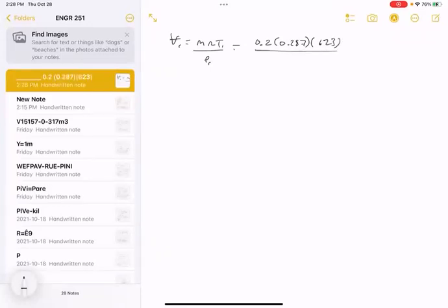The pressure in the initial state, so nothing's happened yet, is 2.5 megapascals. But because this is in kilo, we also have to make sure the pressure is in kilopascals. So this was divided by 1,000, and this has to be multiplied. So we're going to do 2.5.